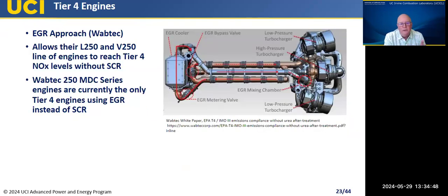Now, the trade-off, I guess, is illustrated on the right, where we don't have DEF, we don't have an SCR system, but we do have to mix in the exhaust gas with the fresh air. We also want to tailor those temperatures, so now we have some heat exchange equipment involved, and so there's some complexity added there. But it's an alternative to SCR and diesel exhaust fluid. So, next slide.